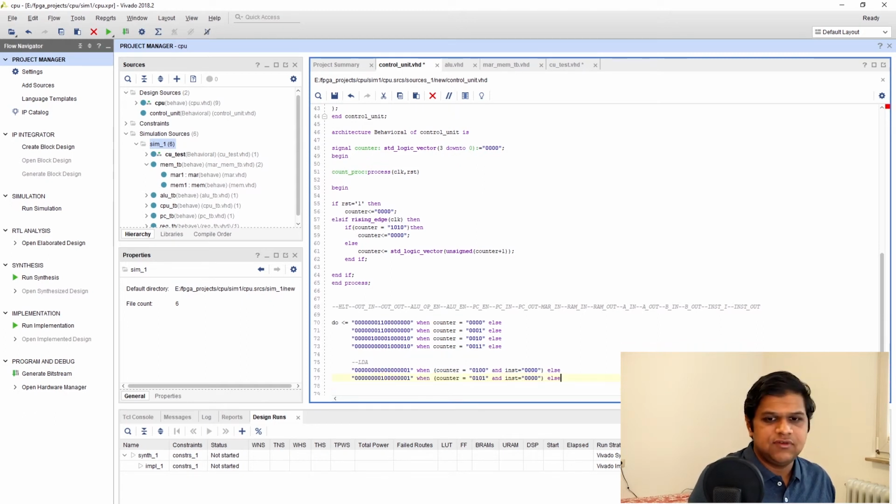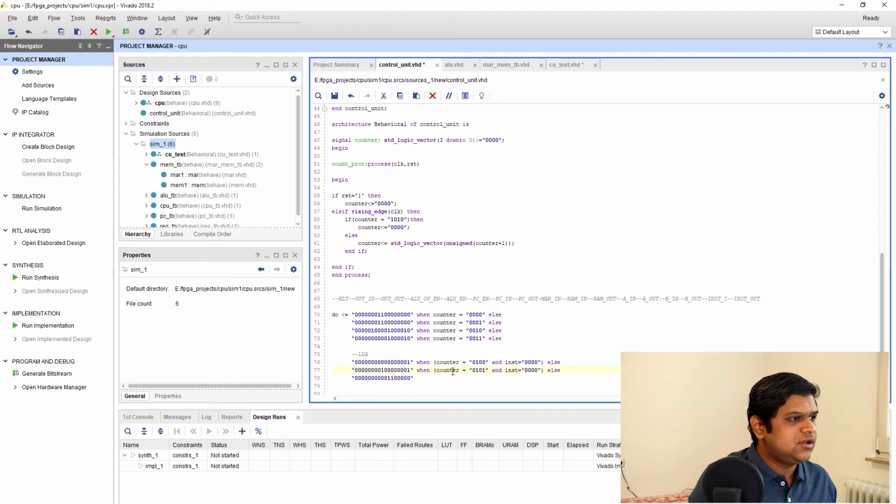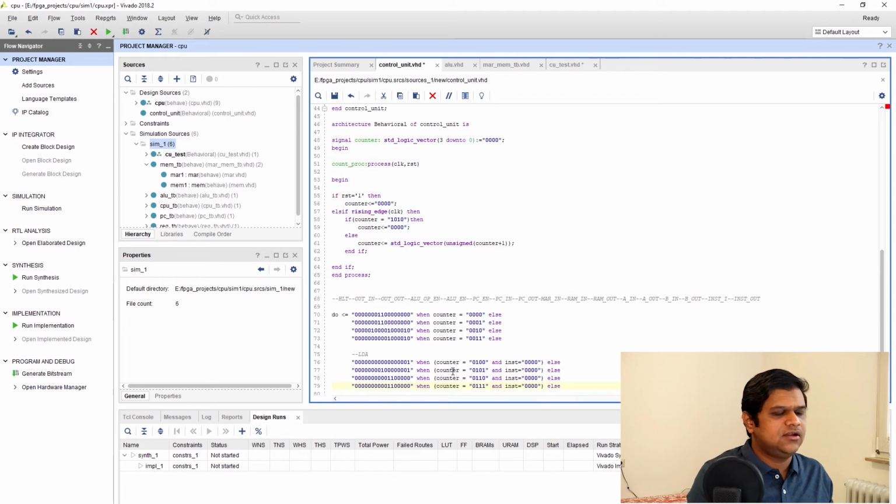And then from memory we will add to register A in the next clock cycles. Weirdly, again this operation takes 2 clock cycles. So in the next 2 clock cycles we will do the same, and that's why this instruction will take a total of 7 clock cycles.